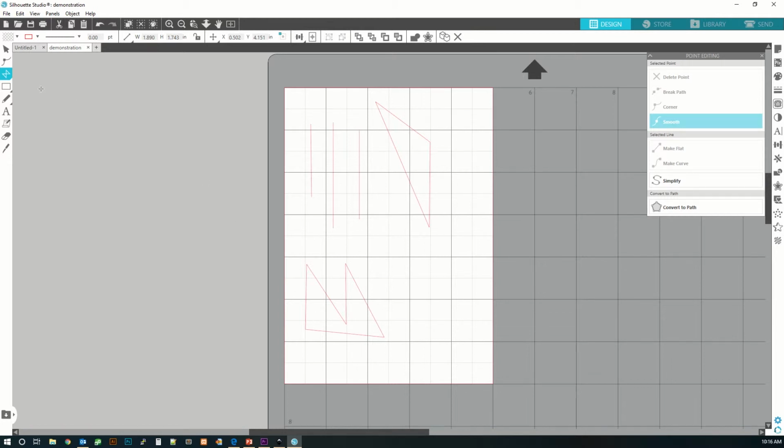The Draw a Curve shape allows you to do a similar thing as the Draw a Polygon, except this time your lines are curved. You can edit the curves of your polygon by double-clicking the shape you drew and clicking on your points. It'll give you a slide bar that allows you to edit the arc of your curves.